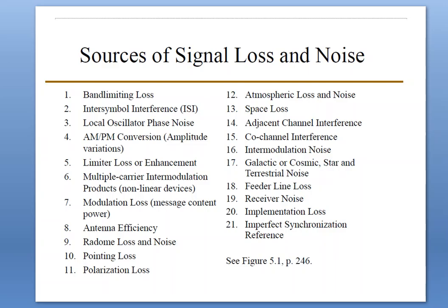The mechanisms contributing to a reduction in efficiency or loss in signal strength are known as amplitude tapering, aperture blocking, scattering, re-radiation, spillover, edge diffraction, and dispersive losses. Typical efficiencies due to the combined effects of these mechanisms range between 50 to 80%.